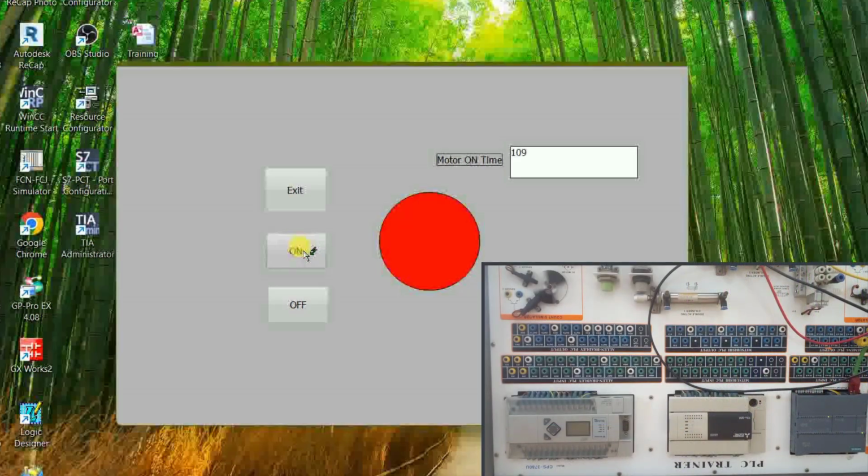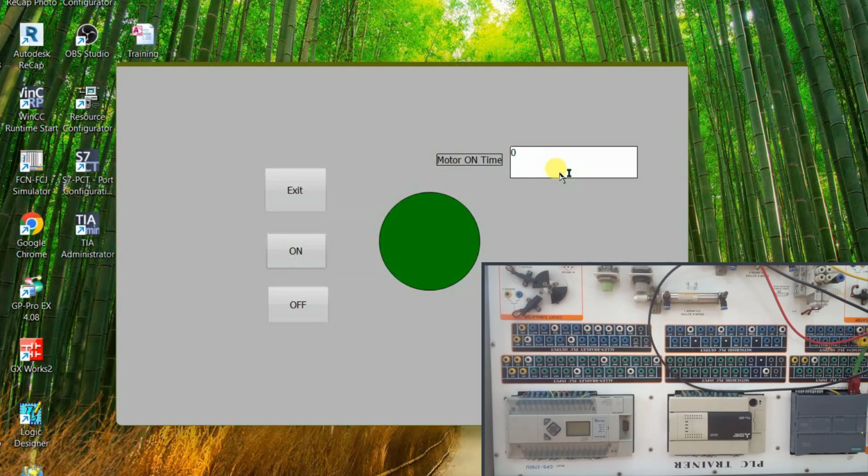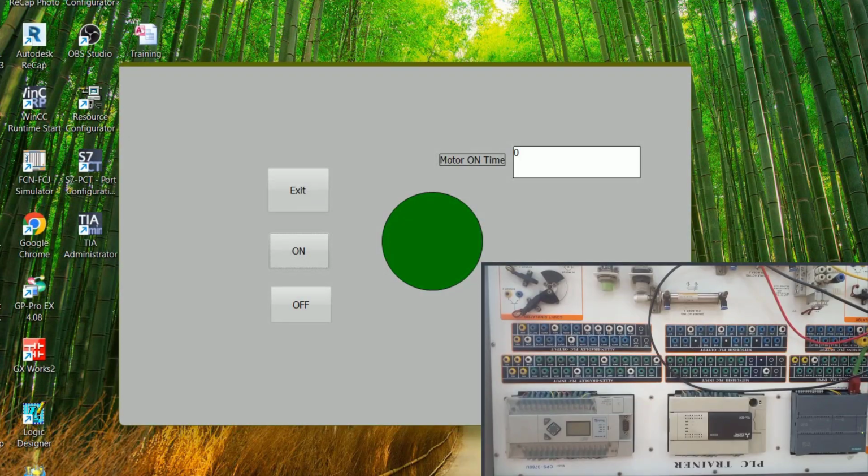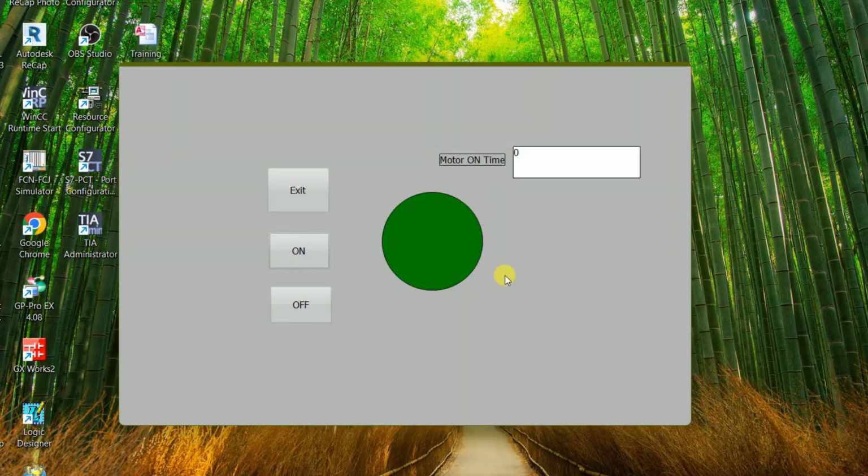Perform motor operation from the HMI interface. Observe, as WinCC project is running now on the server station, we are able to perform motor operation and monitoring activities from the HMI interface of server station. To perform the motor operation from the client station, restart the client PC and log in to client PC using same ID name and password.